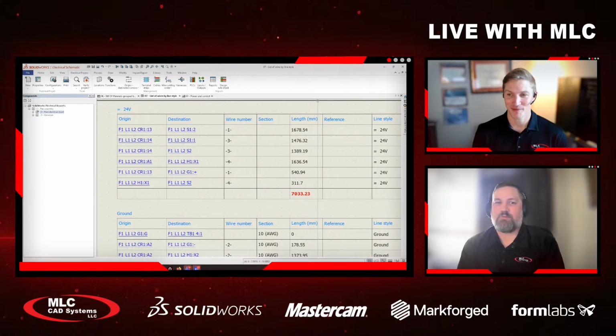I would recommend that you customize these reports and save them. Those are the green reports that you saw that were project specific. So don't make the changes every time, just like a table template inside of a SOLIDWORKS drawing. Make sure that you create a report template for yourself inside of Electrical. And then you're saving it basically anywhere? It doesn't get archived in an Electrical file? You can just save it in PDM or wherever.